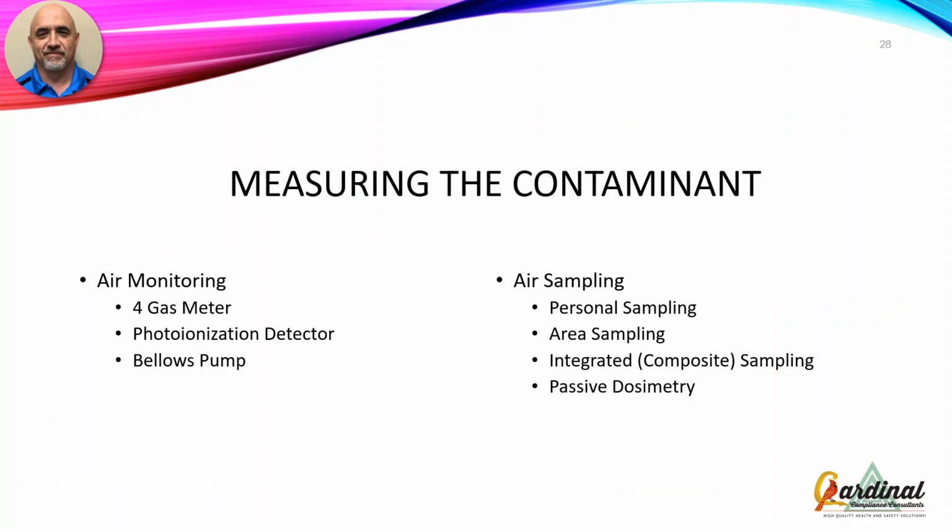So that's when we start getting into putting the science behind what we need to do, okay? Variety of different ways. There's 2 things that we're going to do. We can do air monitoring or air sampling. Air monitoring is like taking a picture, okay? That's what I know is happening at this moment. Air sampling is like me taking video, giving me a longer, big picture. Okay, this is what happened over this period of time, okay?